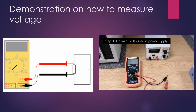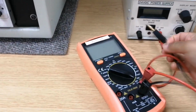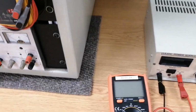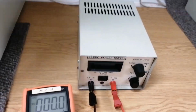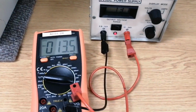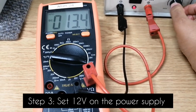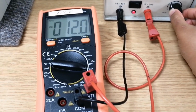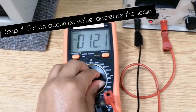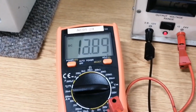I'm just going to open a video on how to measure voltage. In the video we have a power supply and a multimeter. We connect our multimeter to our power supply, and we then select the accurate scale. If I say I want 12 volts on my multimeter, I choose the 200 volt scale. And like I said, in order to get a more accurate value, you have to decrease the scale. So I took it to 20 volts, and note how 12.1 volts changed to 12.19 volts.